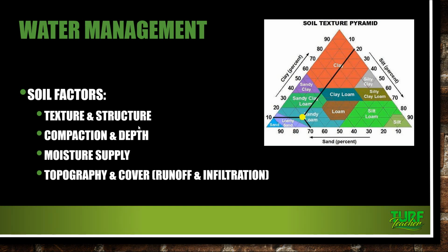If we have soils that are high in salt, we're going to have to apply some gypsum. We may even have to do some subsurface drainage with soils that are high in salt. And sometimes you may even have to filter out some of that salt, flush it out with some clean irrigation water. And you see that happen a lot of times when you're using gray water or refurbished waters, and not using clean irrigation water. You may have some of these salts build up in our soil and some other things as well. But soil factors, it depends on texture and structure.